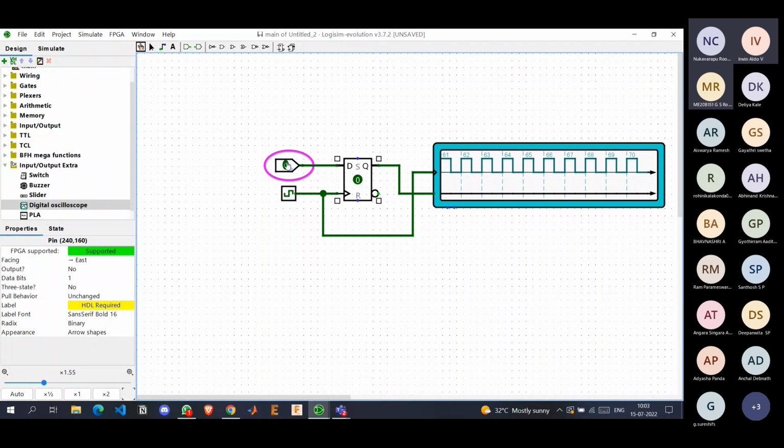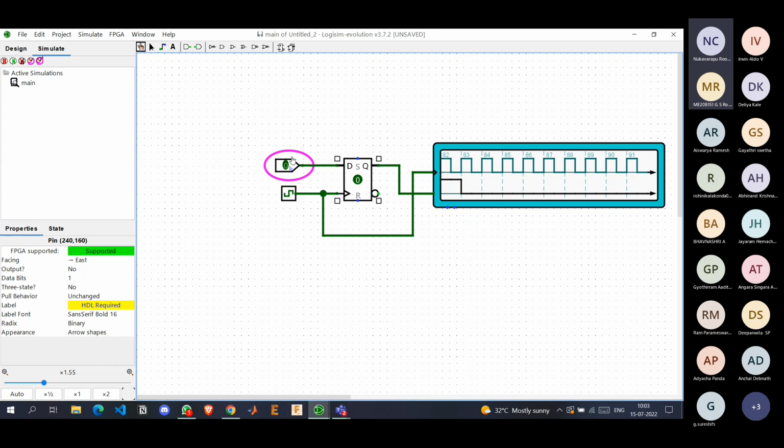See, it's a very simple looking flip-flop. 0 here means 0 here, nothing else. If I press 1, as long as the value is 1, it will be 1. And again, when I turn it back to 0, see, it becomes 0 in the next immediate clock pulse. Turning it on and turning it off. Now I'm pausing the simulation. Now see.